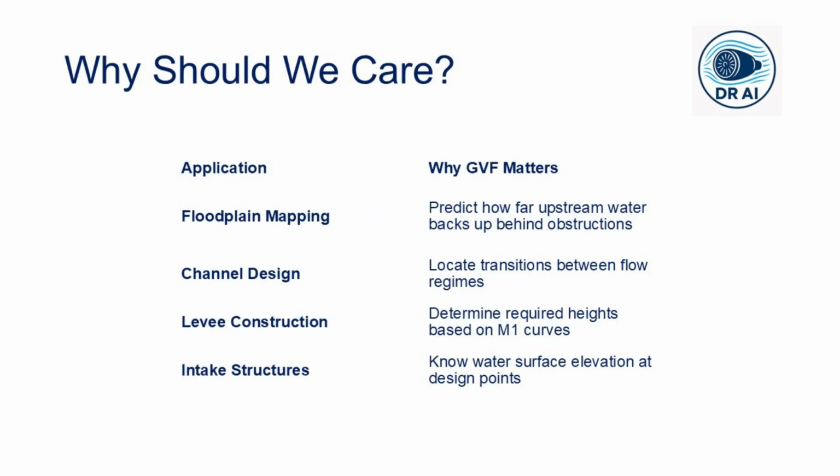So now you might be asking, why is this important? Why do engineers spend so much time analyzing the gradually varied flow profiles? So here are a few practical reasons. Number one is floodplain mapping. When we build a bridge or a levee, we need to know how far upstream the water will be backed up. The M1 backwater curve is primarily the tool for predicting the extent of flooding during high flow